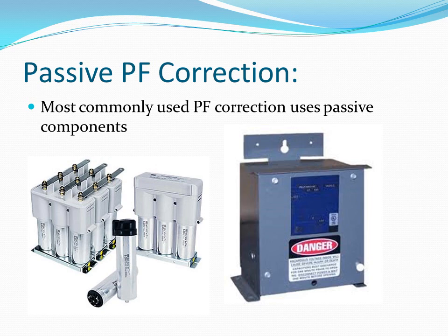Adding capacitors to the system is the most common technique for correcting a poor power factor. It is generally called passive correction and done through installation of shunt capacitors, which are capacitors connected in parallel to the load. The installation of power factor correction capacitors will reduce the kVA demand on the transformer, thereby allowing additional load to be added without transformer resizing. Improved power factor will also help to reduce losses and support the bus voltages.